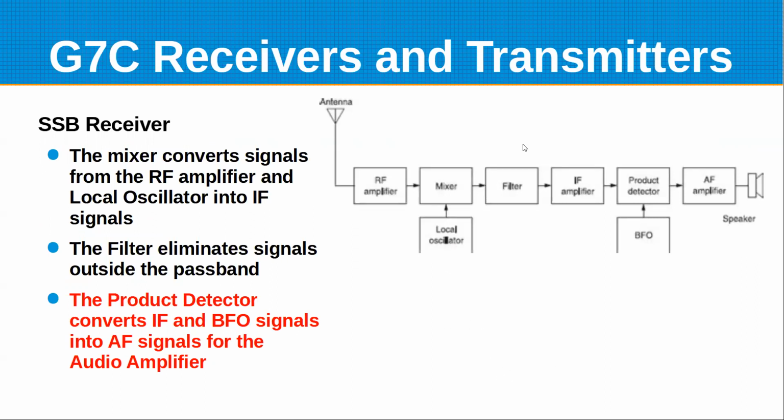Okay. And that's a single sideband receiver. It kind of works opposite. The basic difference they're pointing out is that for single sideband, you can't use a normal envelope detector, which probably comes up on a later chart of what the envelope of the modulated waveform is. That represents the amplitude modulation signal, or audio signal.